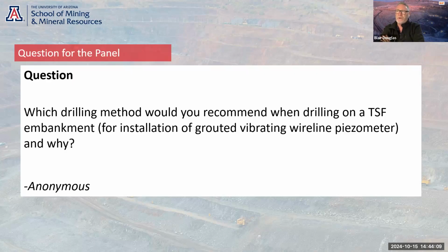So whether it's sonic or traditional coring really depends on the sensitivity of those pressures, as Jeff said. But I think generally the coring methodology, if you can get good recoveries of samples, is also still useful, because not everyone's got a sonic rig in their back pocket that they can just bring out to site. And they are a bit more expensive. They do get held up on rock if it's rocky down there.